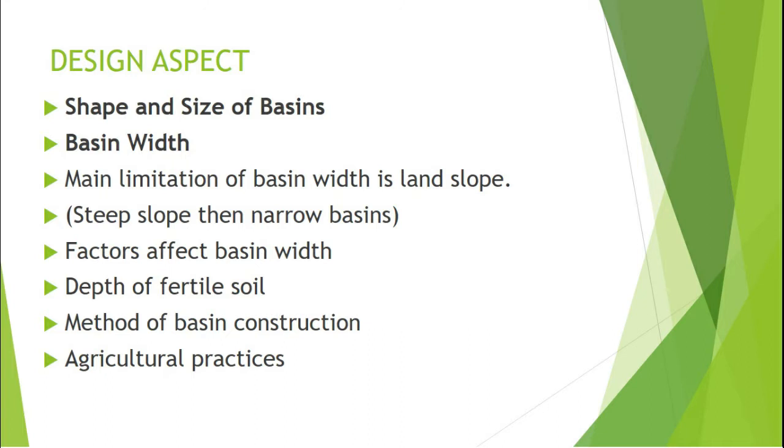Basin width. The main limitation of basin width is the land slope. Steep slope, then narrow basins. Factors affecting basin width. Number 1, depth of fertile soil. 2, method of basin construction. 3, agricultural practices.